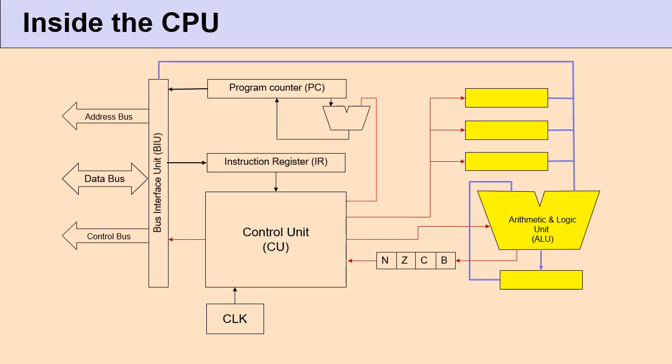So register A, the accumulator, is connected to one input of the ALU as well as the output of the ALU. Now this configuration has certain special features in terms of the instruction set that the CPU has, or more specifically how the operands of an instruction can be specified when the opcode involves an operation carried out by the ALU.